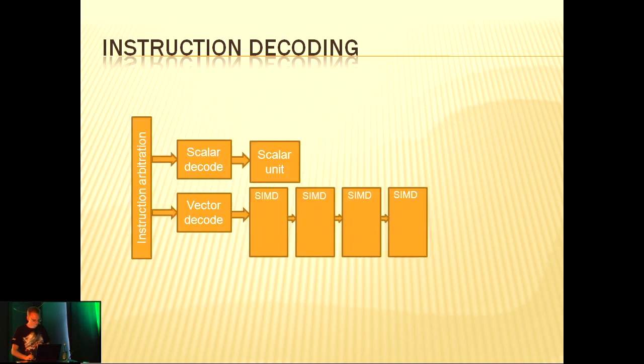So here's basically what happens. The CU chooses one SIMD per cycle going in a round-robin fashion, and each SIMD then does decoding. You also have the scalar unit depicted there. The scalar unit is a separate unit that is mainly concentrated on control logic and has 2 separate pipelines that have specific purposes for that, but mainly flow control.